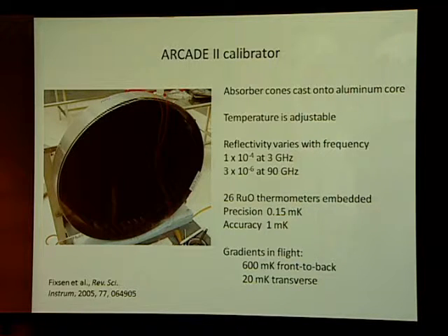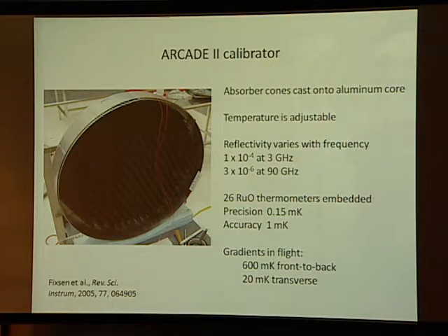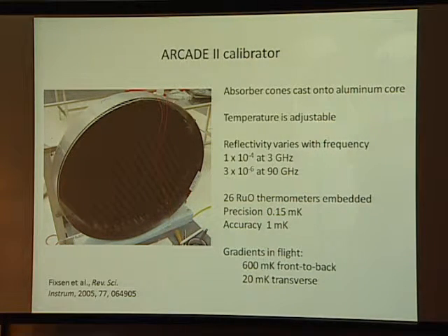We were able to cross-calibrate these thermometers against the NIST thermometer multiple times, separated by several years, and retain this 1 millikelvin accuracy. So I think we're convinced this is a good number for the absolute accuracy. And the precision of the readout is again about 0.15 millikelvin.